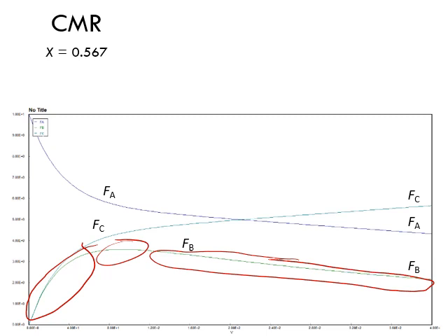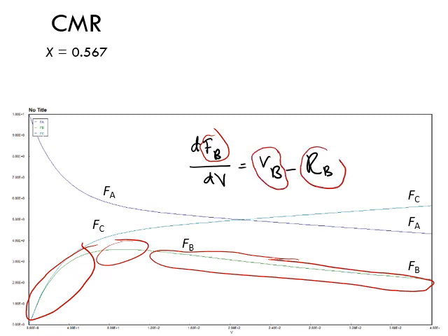Well, let's look at the design equation or the mole balance of B. What was it? It was dFB over dV equals rB minus capital RB, correct? So how B is changing really depends on a competition between rB and this capital RB, right? So when I say dFB by dV, then we are talking about the slope, right? When you plot FB versus V, which we have here, we're talking about the slope. So in the beginning, the slope is positive, right?